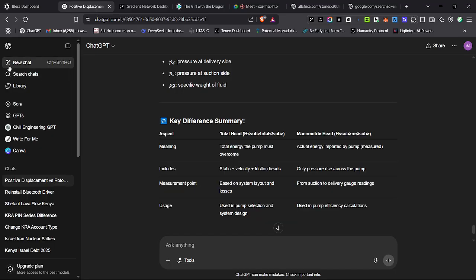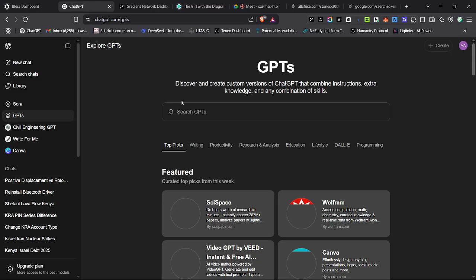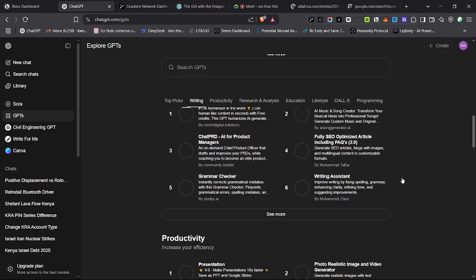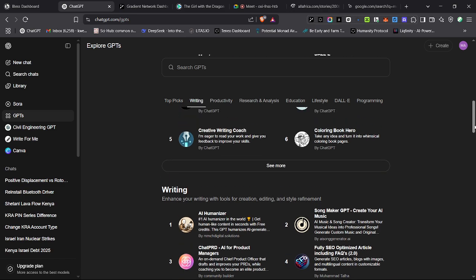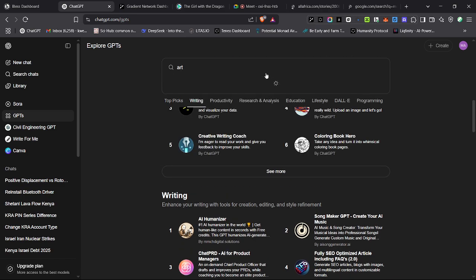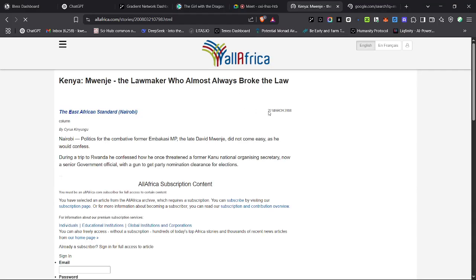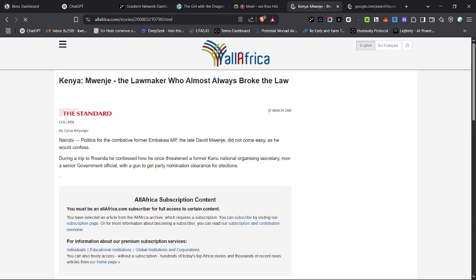rho G Q H by eta, because we have said we can fit a hydraulic turbine at the end, which is equal to rho G Q into H minus KQ squared, which is rho G into HQ minus KQ cubed. For power maximum at a given head H, it will be dP by dQ equals 0. I think I'm on the right track. It is dP by dQ, whereby H minus 3 times KQ squared equals 0, leading us to KQ.